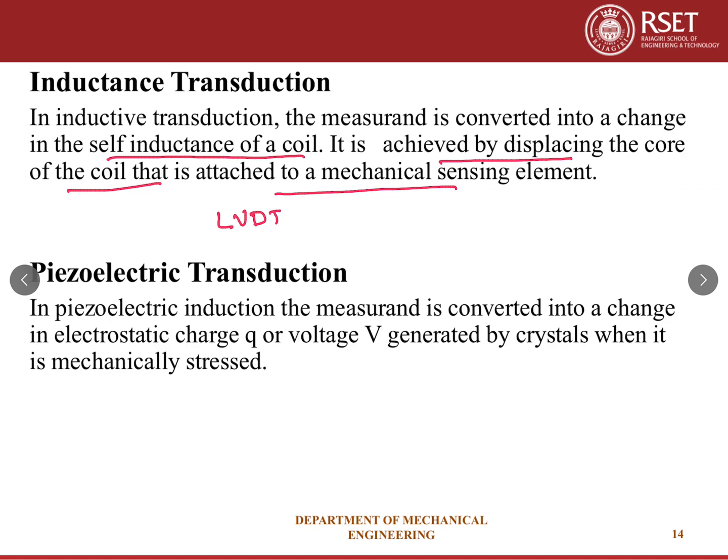Now, piezoelectric transduction. In piezoelectric transduction, the measurand is converted into a change in electrostatic charge Q or voltage V, generated by the crystal when it is mechanically stressed. So we have seen that. Here, when force is applied to a crystal, there is a change in the charge accumulation, and that will give out a voltage. So that is what is happening in a piezoelectric transduction.